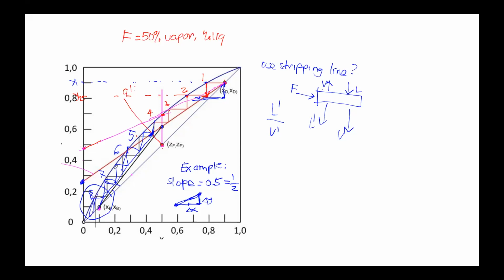So basically, if this is a design question, you haven't made the distillation column, it's still a design, then if you want to have an optimal one, XD over here and XB over here, you need an addition, 9. The new equilibrium stage now becomes 9 stages.